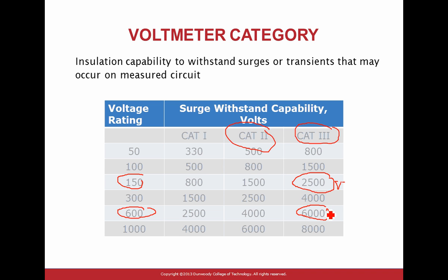A lightning strike hits the transmission line, and look how beautiful the voltage was, nice, going like this, right? And then all of a sudden you get a surge, the voltage goes all the way up, all the way down, and then the surge is gone and you go back to normal. That circuit breaker can handle up to 6,000 volts, 10 times more voltage, because of a surge. That's why these explode. If they get surges and they're not rated for them, these little ones will short. They will ionize the air, short and explode.